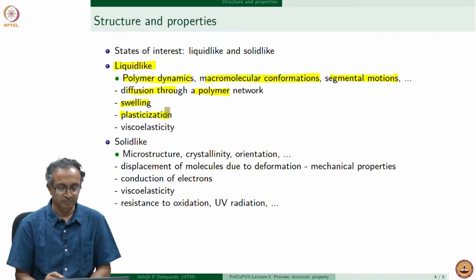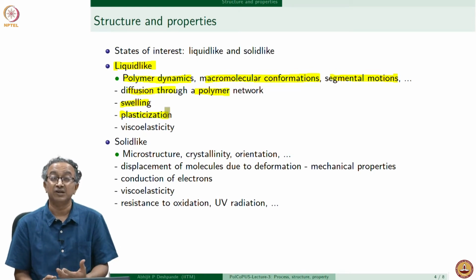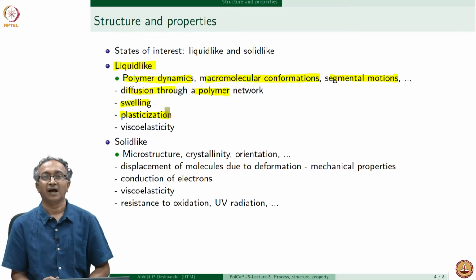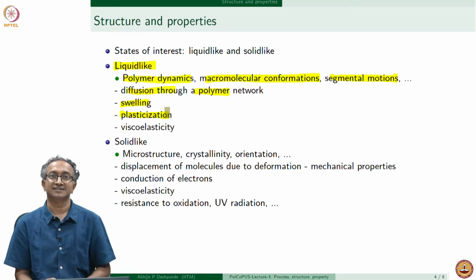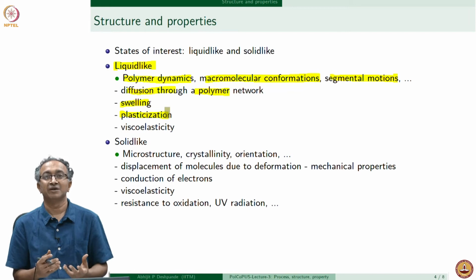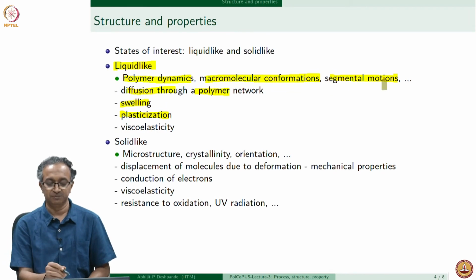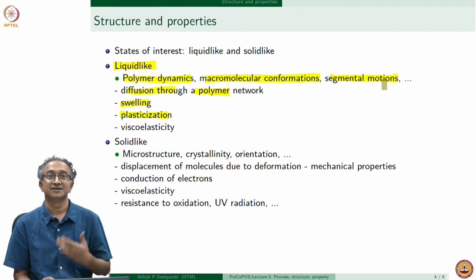Similarly, when I make some object out of PVC, polyvinyl chloride, I can make objects out of PVC only when I plasticize it. So I can add something to plasticize it, I can heat it to plasticize it. Whenever I plasticize something, I make segmental motion possible, macromolecular conformations possible. So these are liquid-like features which we will have to understand.